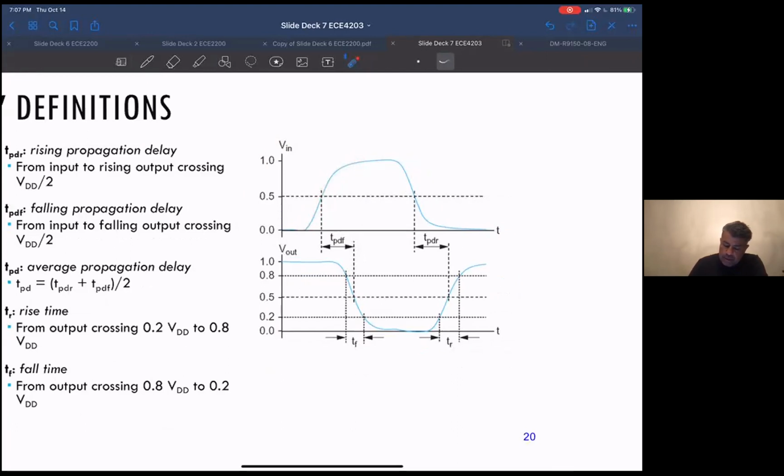So this is probably VN. In all probability, VN is already being generated from another CMOS inverter, because notice it's not a straight up, straight down waveform. There are certain rise and fall times already. It's got these two components, which don't look like a perfect straight line and exponential, but somewhat. You can see this is the straight line portion, and this is the exponential portion.